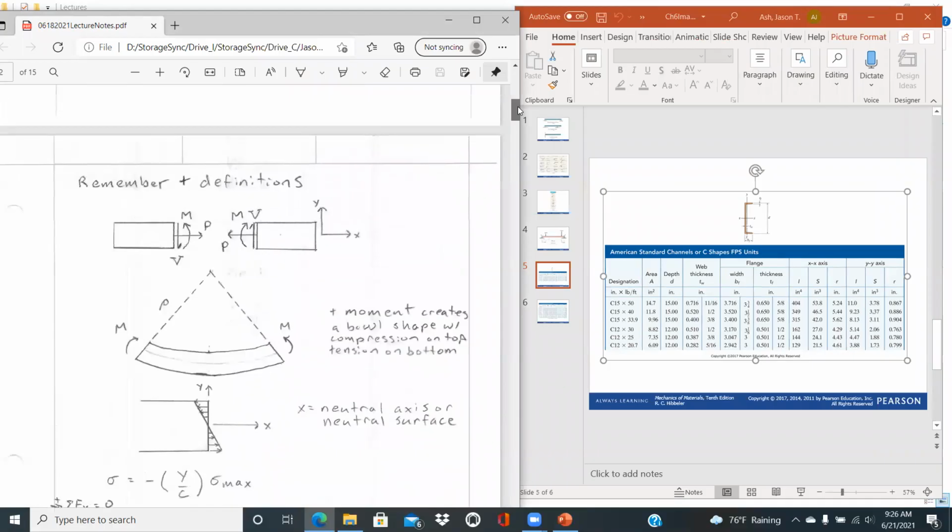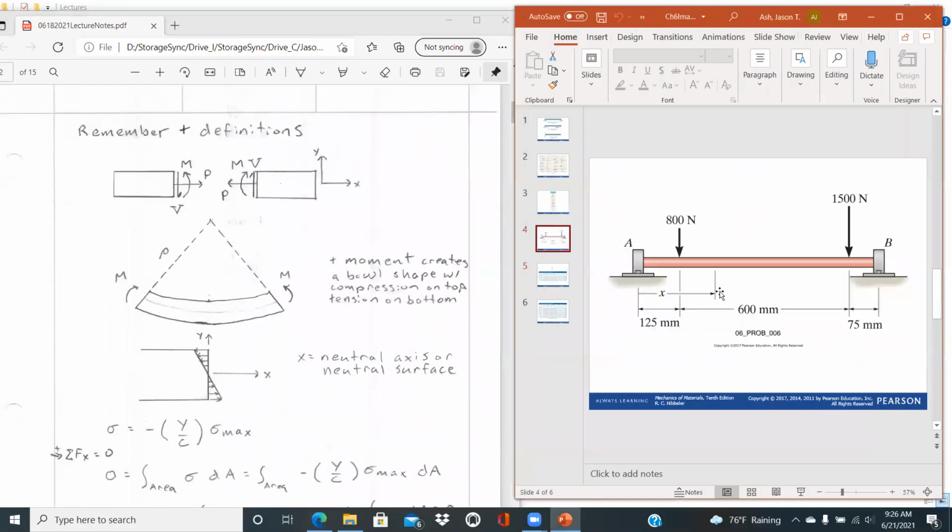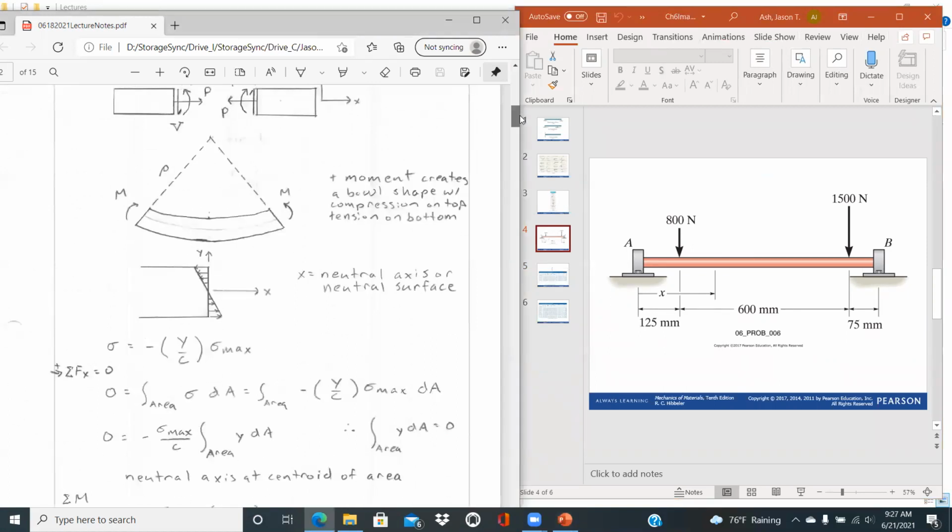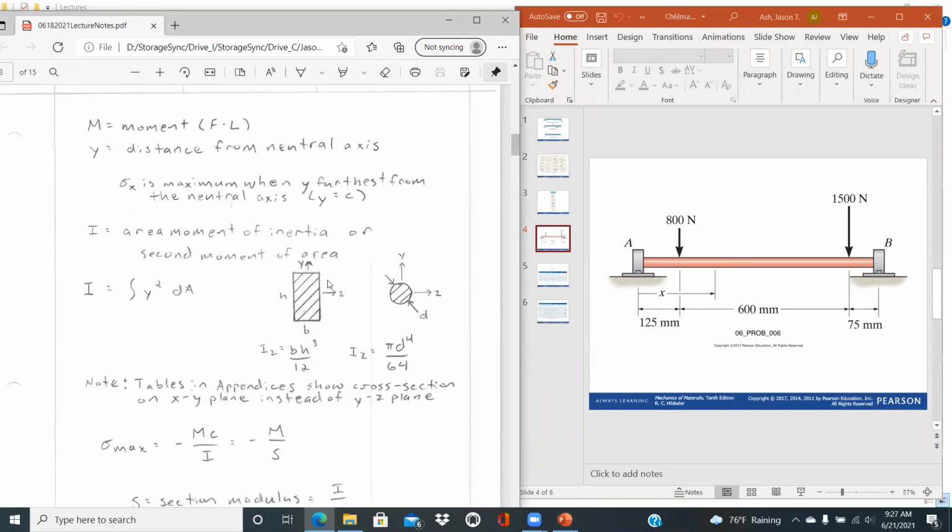typically when you're looking along the length of the beam, this is probably a good figure here on the right to represent that. Your x-axis is usually aligned along the length of the beam. And so when you're solving for your moment, you're going to be solving for that as a function of x. And so when you look at the cross section, that's technically on the YZ plane at that point. And so I've made that distinction here for that case.